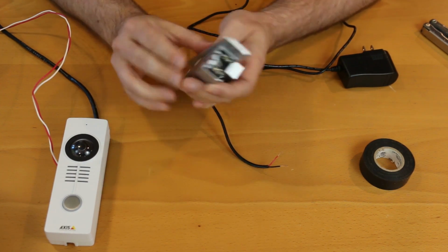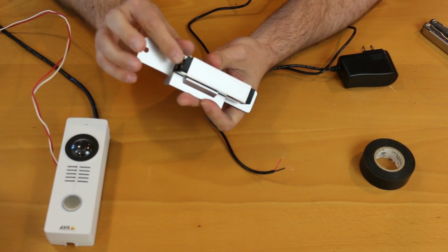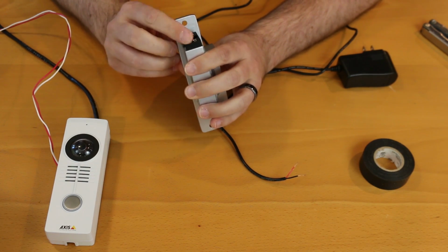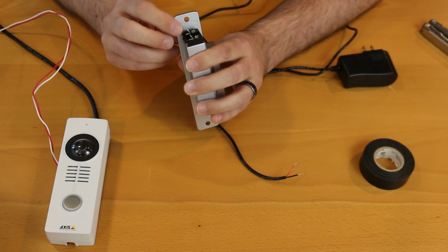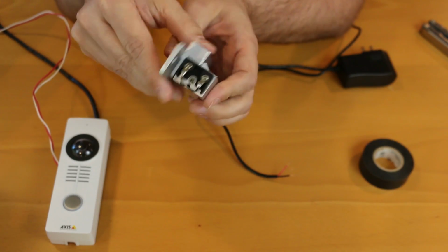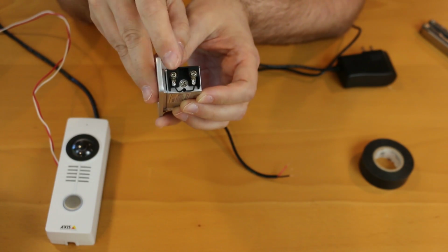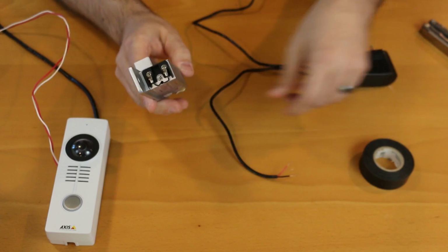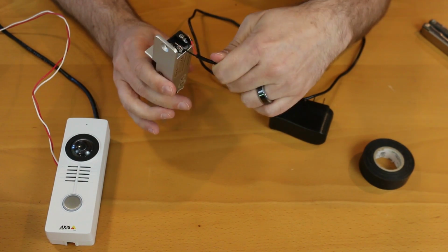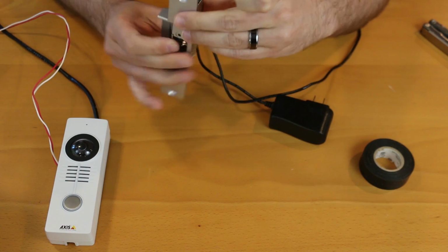On the door strike device, I have one side here that has 3 contacts, yellow, white, green, and I have a second side that has 2 contacts with a black wire going to both. This is the side that I'm going to be focusing on, the side with 2 contacts. Now, this is where we put our red and black wire. Typically, if I have this powered in and I connect these two, then we are going to be open.